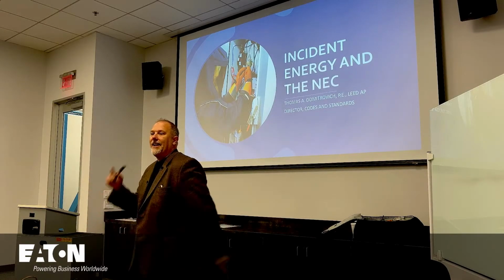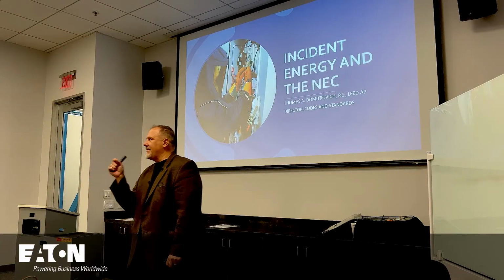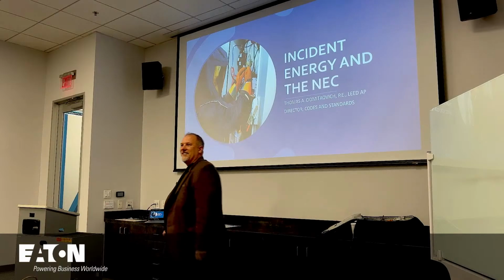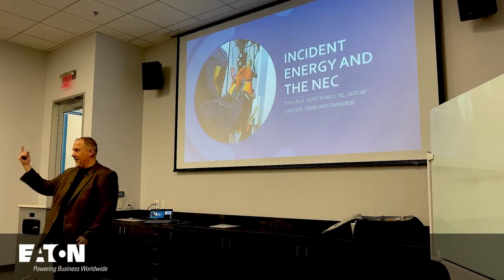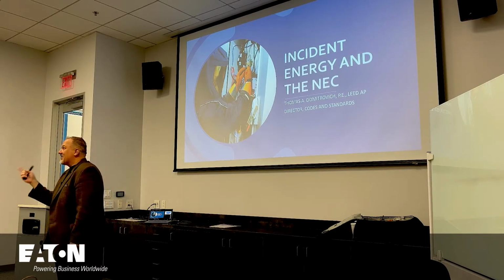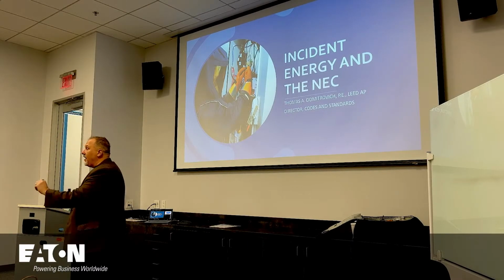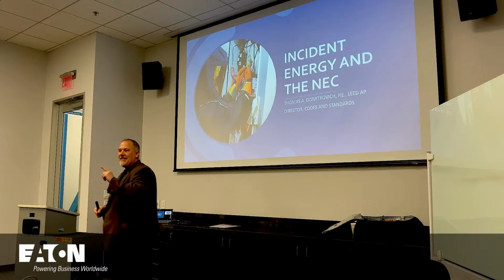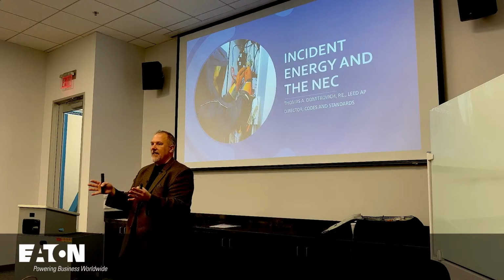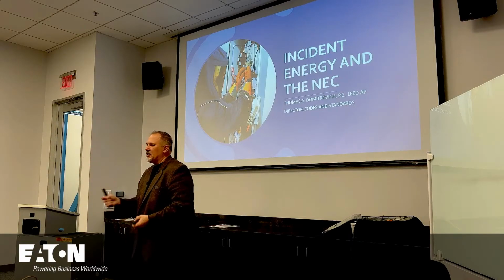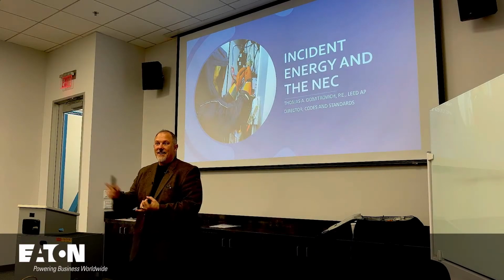The 1971 code had the very first technology in the National Electrical Code to address incident energy. What do you think it was? I'll give you the first two words: ground fault. Not circuit interrupters, GFCIs are for shock protection, but ground fault protection of equipment. Why in 1971? Because three things occurred up until that point. What types of systems, most industrials, did they have? Grounded or ungrounded? Ungrounded, and then they moved to what?